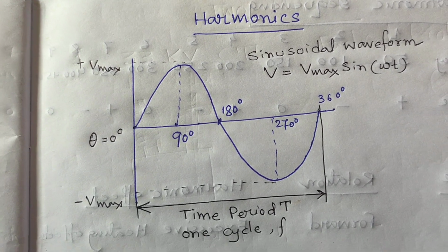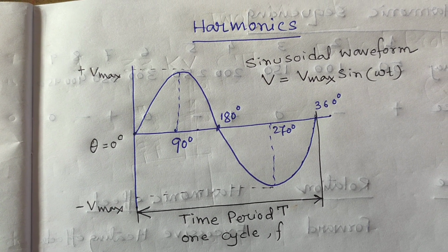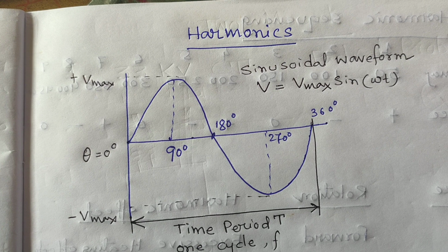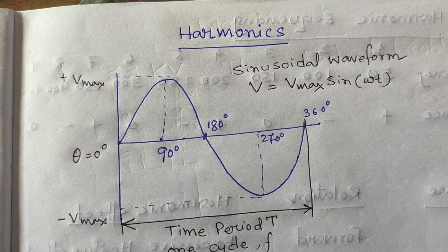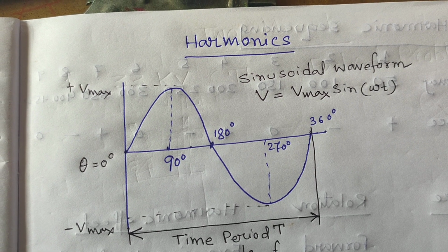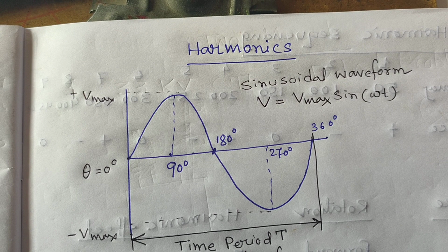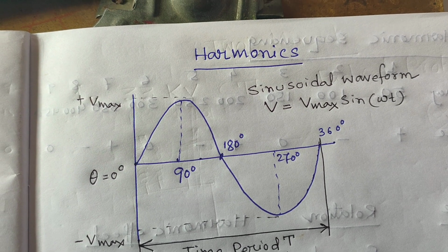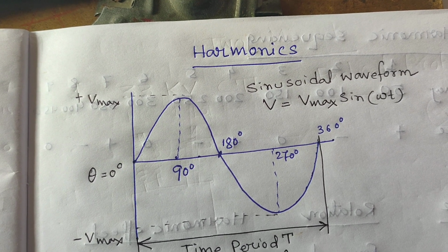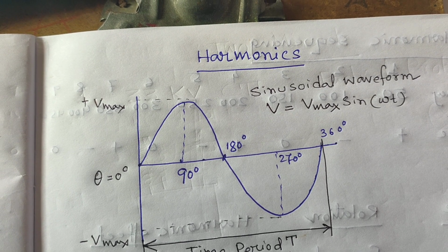Harmonics have only been around in sufficient quantities over the last few decades since the introduction of electronic drives for motors, fans, pumps, power supplies, switching circuits such as rectifiers, power converters and thyristors, power controllers, as well as most nonlinear electronic loads and high frequency energy saving fluorescent lights.